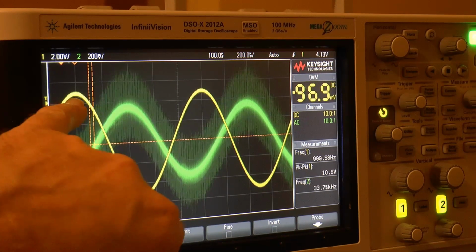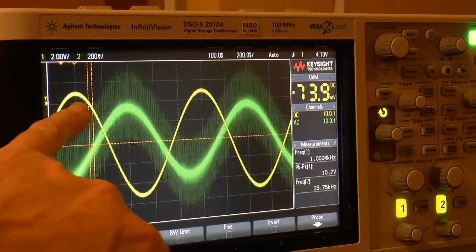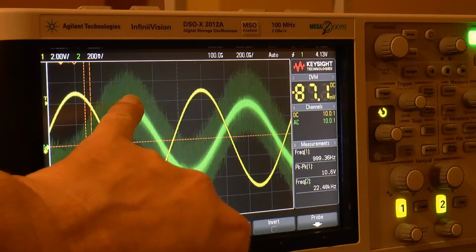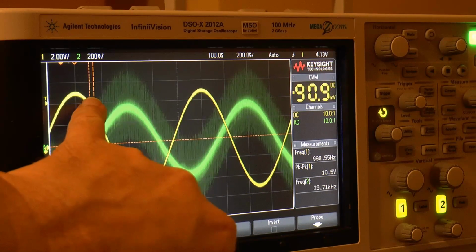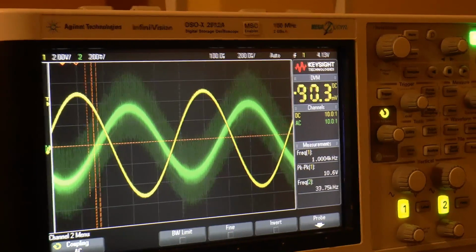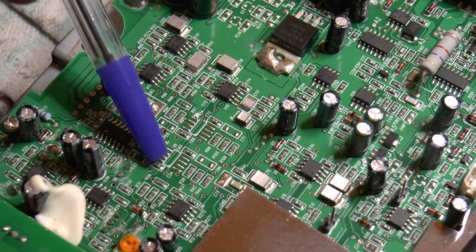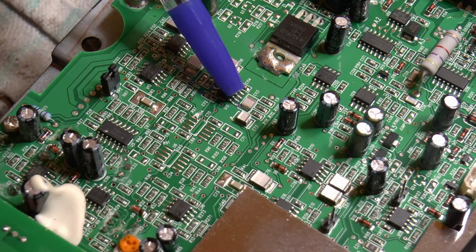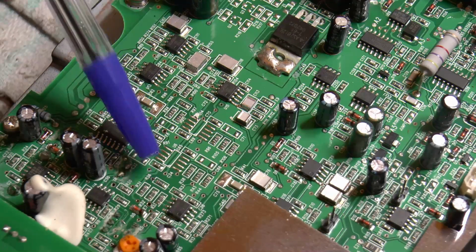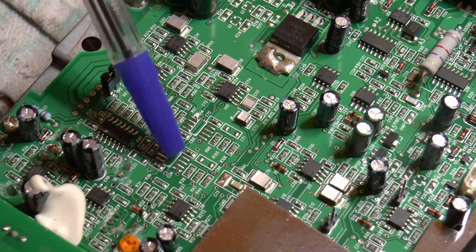And I was looking, I thought, that's 200 microseconds a division. So 200, 400 microseconds. And I remember looking at Mackie's circuit drawing. If you've ever repaired one of these amps, there's spaces here for 2 more op amps, and each op amp has got 2 stages inside, so they did nothing but cause 170 microsecond delay.